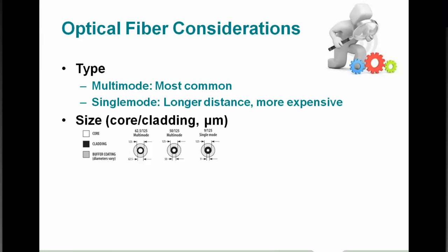Looking at the data sheet for the fiber media converter, it'll probably give you performance specifications for both the 62.5 micron and the 50 micron, and tell you that your distances vary a little bit based upon what you want to use. Typically, you'll find the 62.5 is the more common. And by the way, a lot of times that fiber gets installed by a specialist.